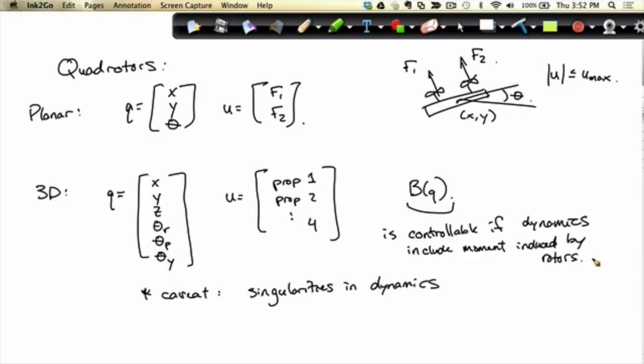I would say the mesh-based dynamic programming is not viable there. But the linearization for the quadrotor with big enough motors works extremely well. If you're thinking about the torque limits a lot, and I said that F1 and F2 can only be positive, you might think, oh, I'm living right at the limits of my torque limits. But in fact, I have to have non-zero F1 and F2 just to find my fixed point, just to hold myself. So I'm linearizing around someplace in the middle of my torque space, hopefully. And sure enough, these things just work, right?